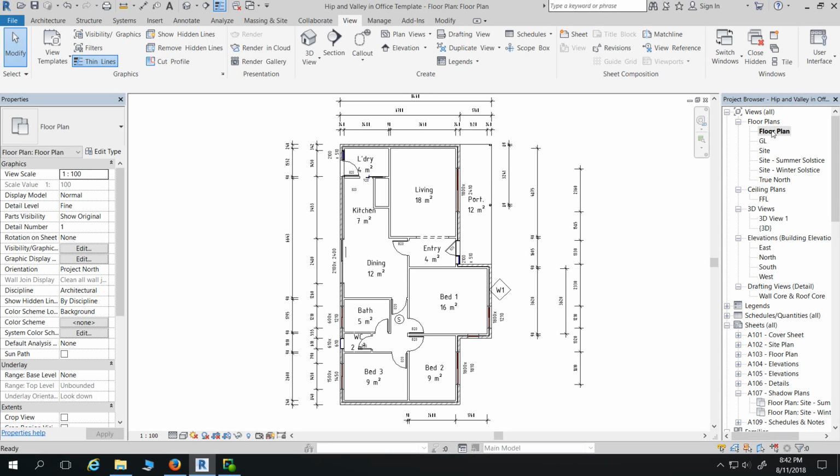You can also create other elevations. If you had a courtyard in the building, you can create elevations to look in that courtyard. If you want to do internal elevations, that's where you'd find them. Please don't use sections as internal elevations like I know someone did and it took me a day to fix it.